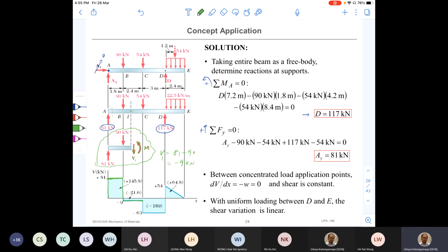And at C, if you want to find out the shear force, you need to cut the beam between C and D. Now you can imagine it in your head and directly write what that value is. Let's say that point is 2. Then what is the V2? We can write V2 by observing the cut portion. See whether you can write it with me.